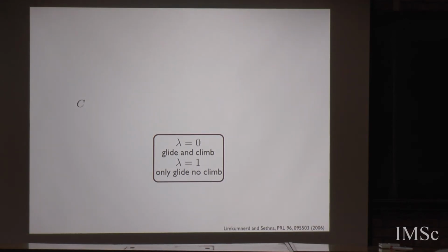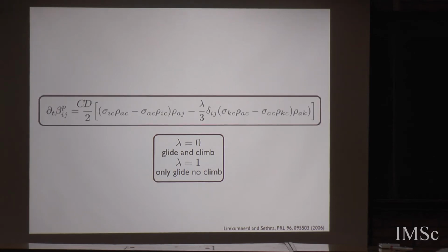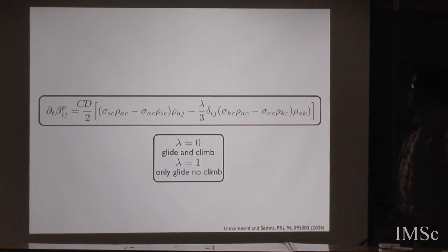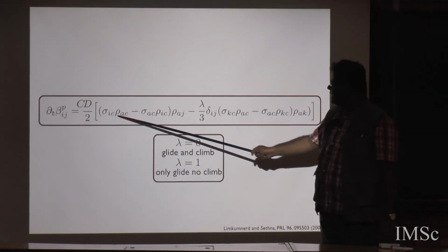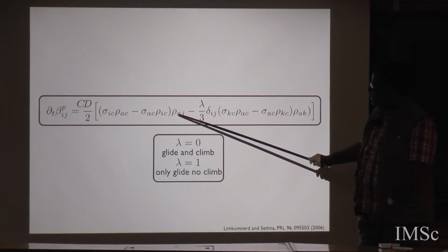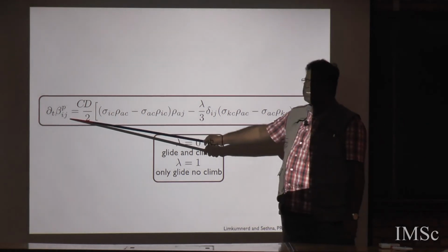Now we will do the same trick as before. Go to that book and find out the most general expression for the eighth order mobility tensor for an isotropic solid. Put that in, do all the algebra, and finally obtain the equation of motion for the plastic distortion field, which you will see involves stresses, and the dislocation density elsewhere, which can be related to the plastic distortion field again.